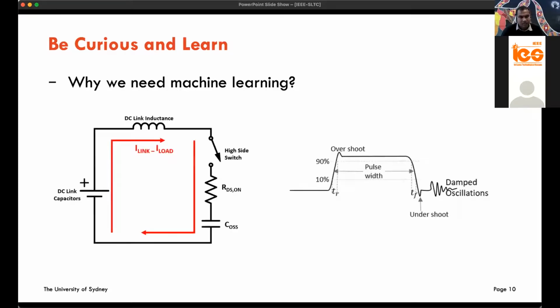If you look at classical systems, this is what we learned. This is a very simple example. If you have a system and a switch, with a little bit of overshoot and damping, at the end of the day, if you want to see if the switch is on or off, you can put a simple threshold somewhere around 90% of the pulse, and then measure it in any electronic system, like a simple comparator. Even in an analog to digital converted system, it's just a simple if-else statement.